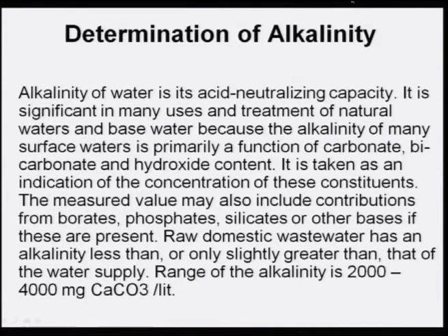The measured value may also include contributions from borates, phosphates, silicates or other bases if these are present. Raw domestic wastewater has an alkalinity less than or only slightly greater than that of the water supply. Range of alkalinity is 2000 to 4000 milligram calcium carbonate per liter.